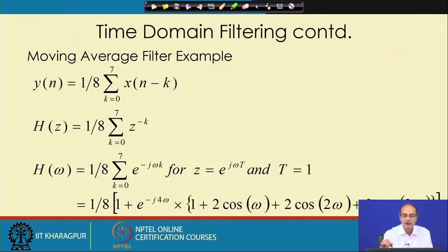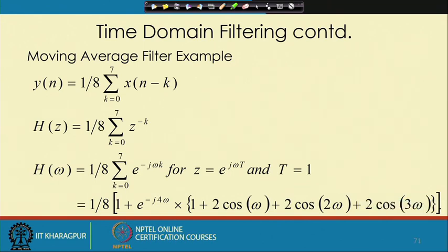So, next we look at one such filter that is taking actually 8 taps, and here we have taken special care that again it is an integer filter, but it is a uniformly weighted filter. If you look at the tap weights, it would be just like a rectangle.